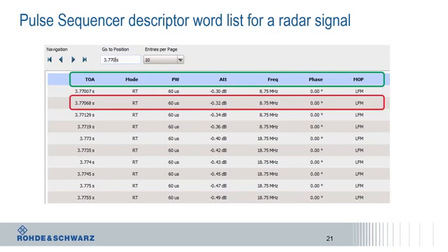And here is how we do this. Instead of calculating a long waveform, we do it differently. We only calculate a control list which has the pulse width duration, a certain attenuation, a certain frequency offset and a phase offset inside. In addition, it carries what kind of modulation it is, and it also carries time of arrival information. This means with this control list, we reduce the required waveform size to a very small value and can do the signal generation in real time in the ARP of the signal generator. This brings down the waveform size dramatically.